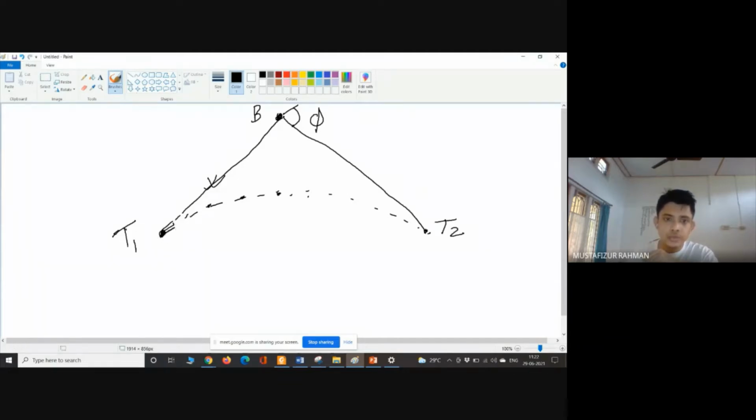So if we go 20 meter along this direction, what will be this angle? So that is our delta 1. Okay, we will find that value. If we know that value, we can have some instrument of angle measuring, and we can give that angle here from this point, and we can look along this side, and we know this distance, and we got this point, right?